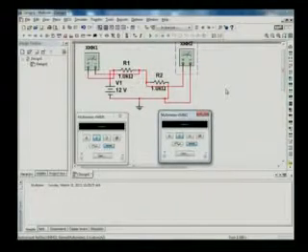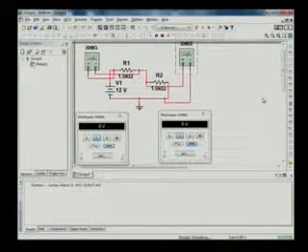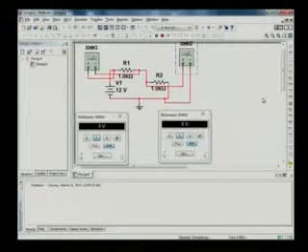We have connected the circuit, now we will simulate, that is we will run the circuit. That green button is there. Okay, you will see 6 volts, 6 volts. So the voltage across R1 we are getting as 6 volts, and the voltage across R2 we are getting as 6 volts. Those results match what we did theoretically, so they are matching with the simulation, right? Then we should approach mounting the circuit on PCB.